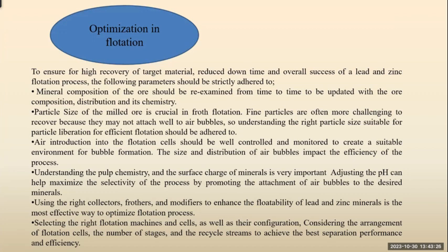So let's look at optimization in flotation. How can we optimize flotation? Particle size is very, very important. You have to understand the particle size. That is, particle size means how fine did my ball mill grind the material that I'm doing? Is it too fine or is it too coarse?